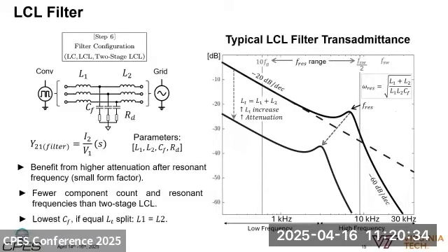And also we could increase the inductance, then it's like shifting down the transadmittance plot, and also shifting a little bit to the left because the resonant frequency changes a little bit, but then we have a bigger filter. But these are the parameters we can play with so we can achieve the attenuation required.